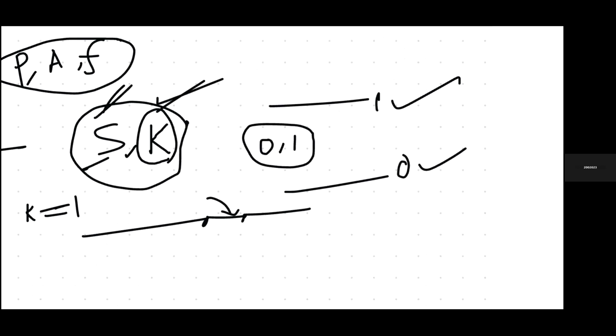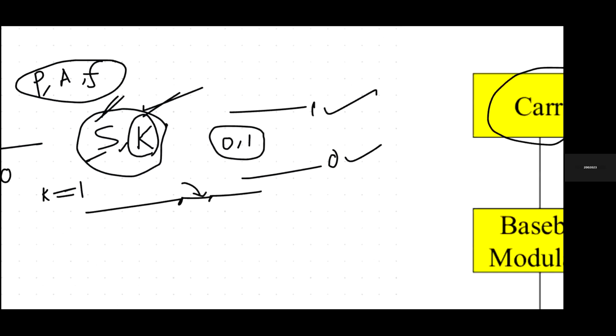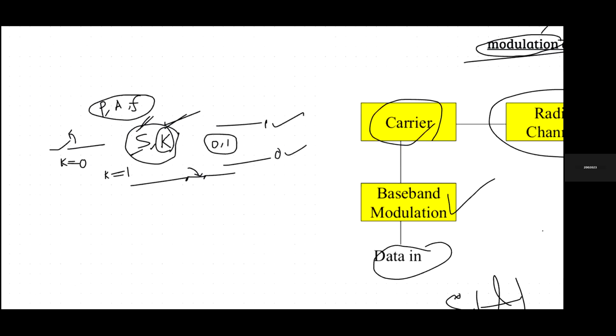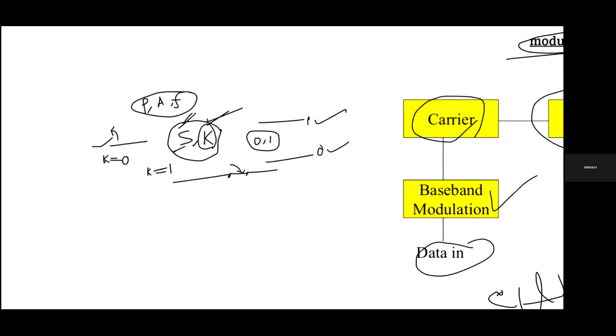What does shifting mean? Shifting means the properties of the transmitted signal, which are phase, amplitude, and frequency, are shifting between two levels. They are 0 or 1. We already know that the digital signal includes two main signals, 1 or 0. So the basic properties of the transmitted signal, their phase, amplitude, or frequency, are also shifted between these two states or levels. So this is shifting of the signal.